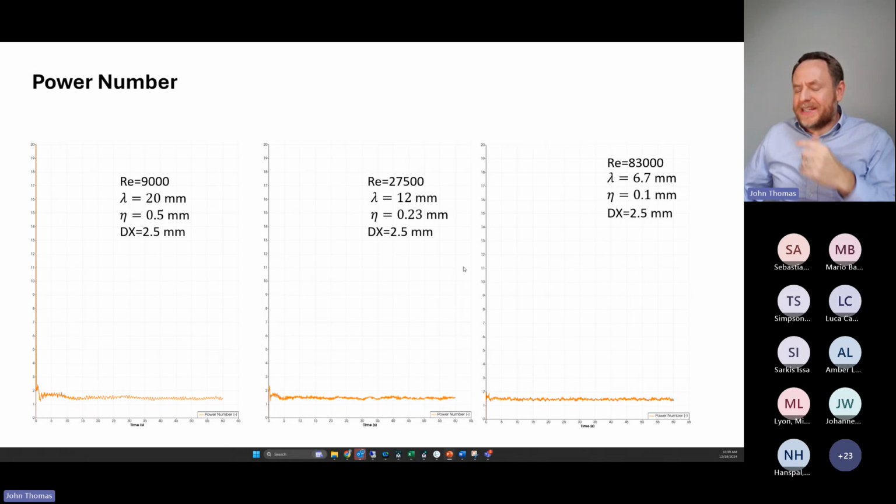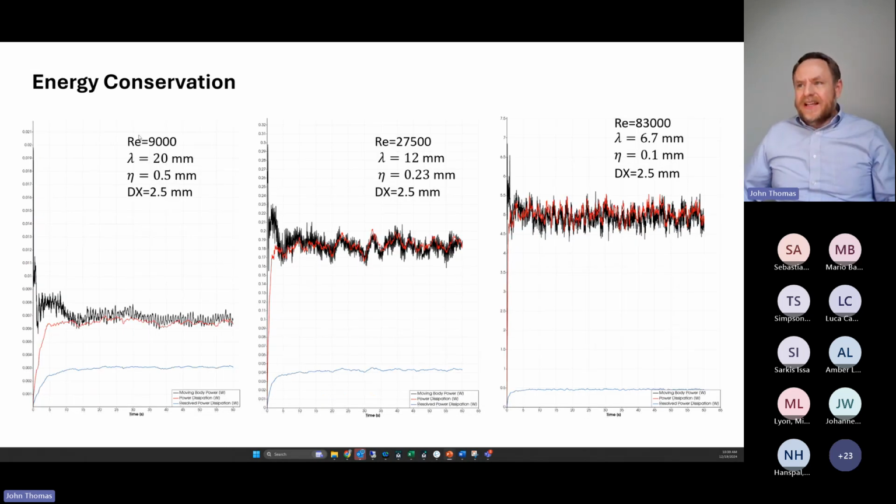Now let's look at energy dissipation rate. So here again, same lineup, 9,000, 27,000, 83,000. I've got power on the left axis. To be careful, these scales are shifting because they're so different. As I go from, and these are all achieved by changing the impeller speed, this is impeller speed of 20 RPM, this is 180. We know that power input changes as n to the 3rd power, and so I couldn't put these on the same scale. But that's not the point I'm trying to make here.